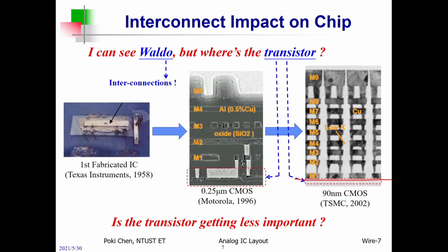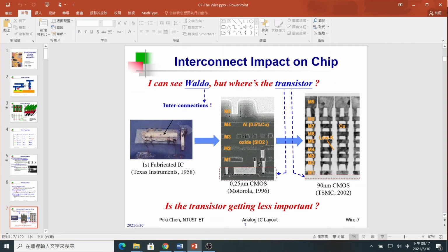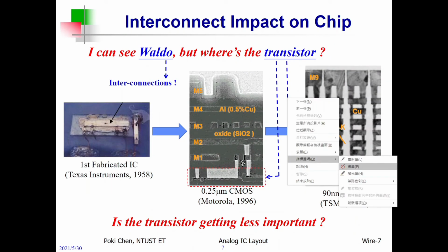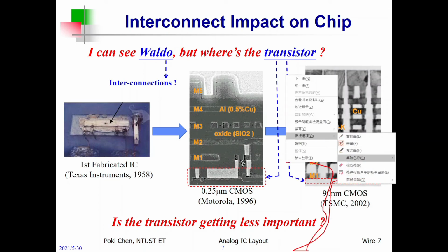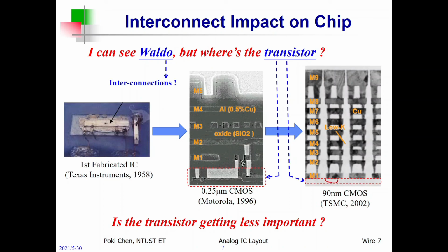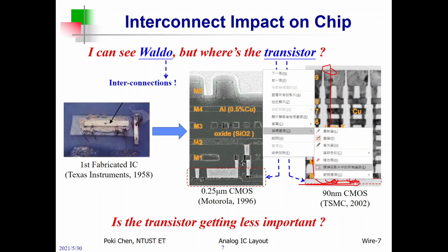And we try to diffuse into the surface of the wafer or substrate to make your N plus or P plus region for such a transistor. So you have your source region, your drain region, and above it, the gate, above the surface. But even above the surface is metal 1, metal 2, all the way to metal 6. All of them will carry the current to go through the source to the drain and backward to metal 9. So according to such a three-dimensional structure,